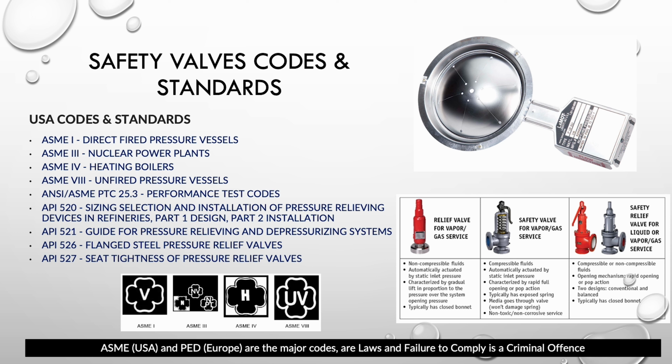Absolutely. Just think about the layers. The safety valves are literally there for when your process control failed. The process control itself failed. Yes. Your tripping system failed. Beyond the process control, you have a tripping system that is supposed to engage whenever something dangerous occurs, and this layer also fails. This is literally the last layer for you to be controlling anything. 100%. Because beyond that, that's where an event will be reported.